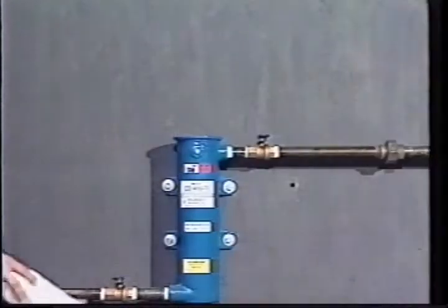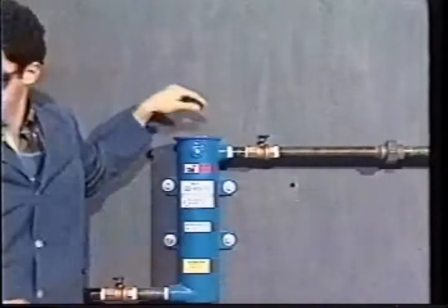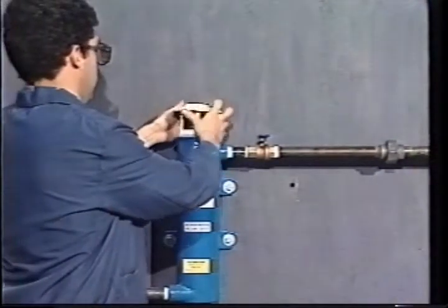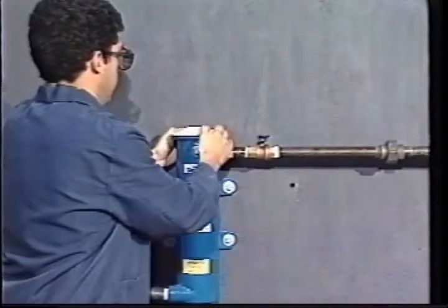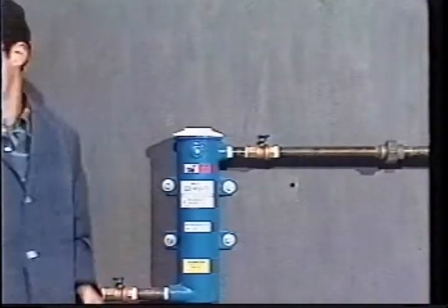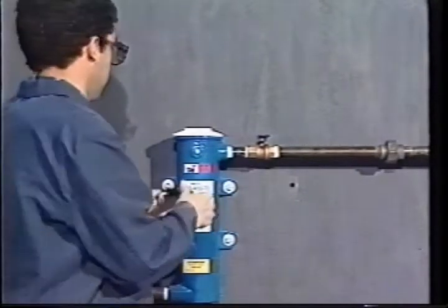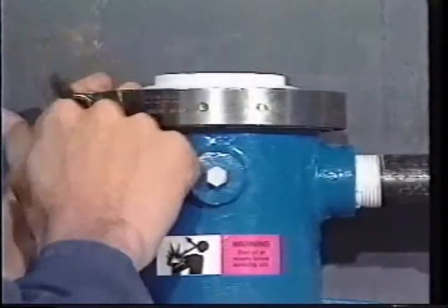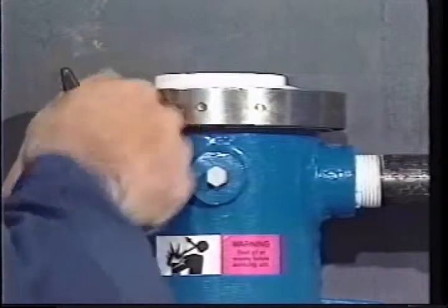The form-fitted desiccant bag fits into a cast aluminum housing, which is finished with a polyurethane powder coating inside and out. This results in a smooth interior, allowing for easy assembly and installation of the bag. Filter discs attached to the cover fit snugly on the smooth interior sidewalls and seal the unit for final filtration. A V-clamp, equipped with disengagement knobs, effectively seals the unit's top cover.